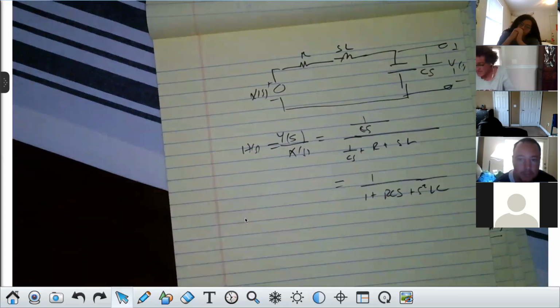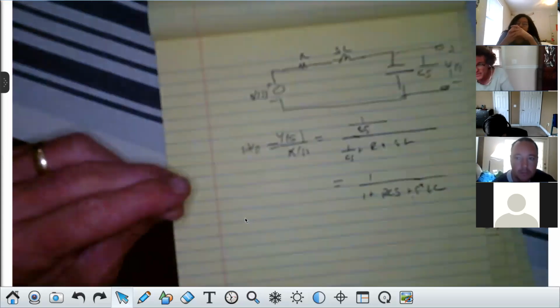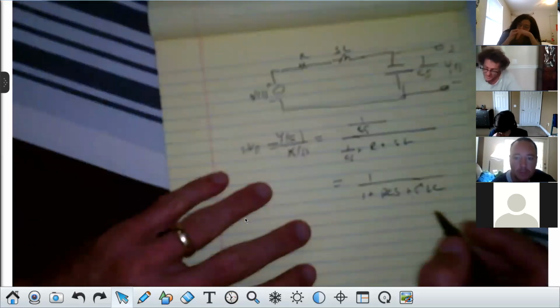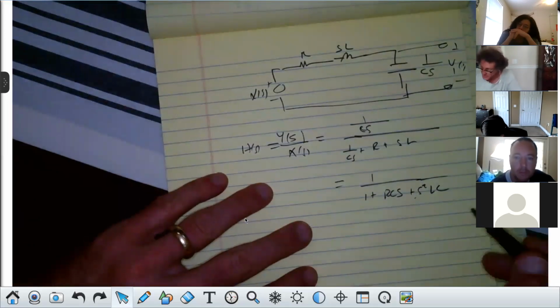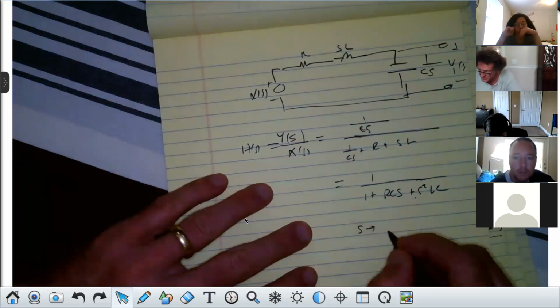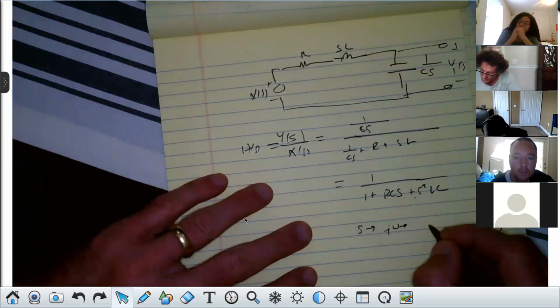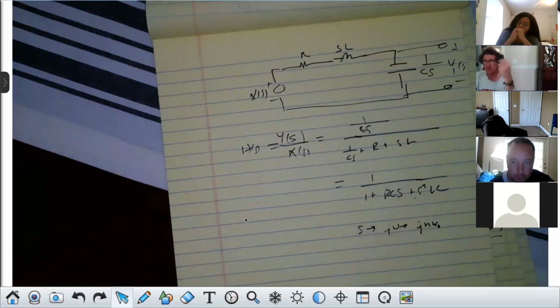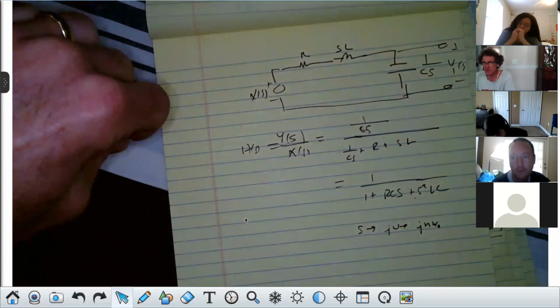Now, you don't want that S squared to have any kind of a coefficient if you're going to do inverse transforms to get h(t). It's sufficient the way it is if you wanted the filter response, because then you would first let s equal j omega, and then you would let omega become j n omega naught. And the n indicates the order of the harmonic: first, second, third, or which harmonic it is. But you don't use a Fourier transform per se, you use Laplace transforms when you're doing this work, usually.